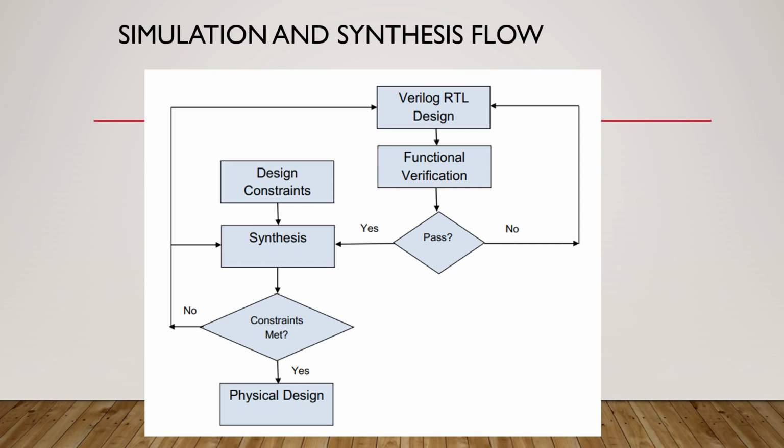After describing your functionality by using any HDL language, that can be given for the functional verification. For example, if you are designing an 8-bit adder, you have to verify whether that 8-bit adder is actually working as an adder or not. So we have to check the functionality here by using different test fixtures, that is, different combinations of test input vectors given at this stage to verify the functionality of our design.